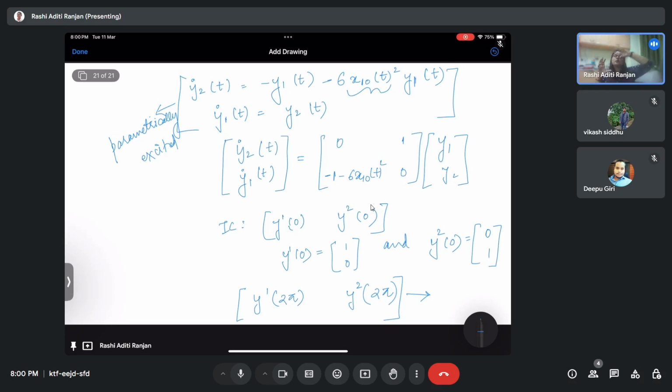Okay, first we learned about how for the linear system, we first calculated the fixed points by putting the acceleration and velocity to 0. After calculating the fixed points, we tried to plot the graph of x versus x dot, and on the basis of that, we were seeing whether my system is converging at a fixed point or diverging from the fixed point. When it was converging, we said that the fixed point is stable. When it was diverging, my fixed point was unstable.